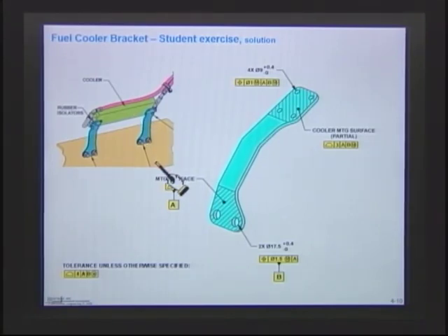Well, if we're going to do that, we're going to have some problems here. You can tell that right away. Remember how we talked about those holes right there? They're so close together. We had a lot of tolerance on them. And if they did, you can see these brackets. This bracket's going to hang this way. This bracket's going to hang this way. They're going to be hanging on there loose.